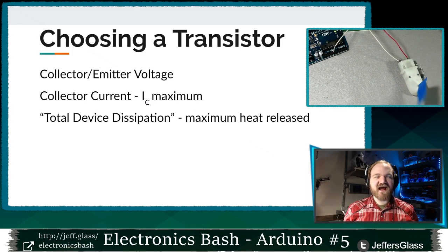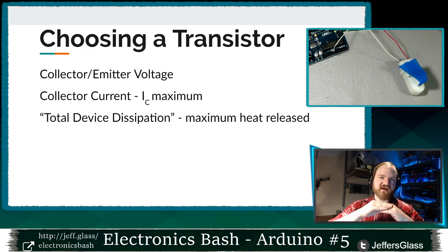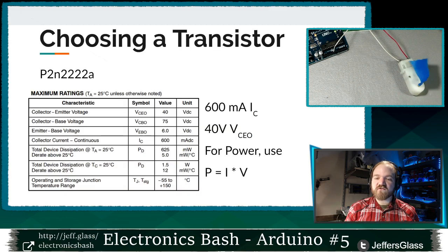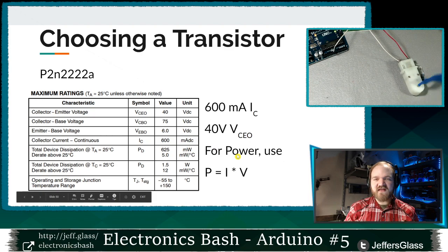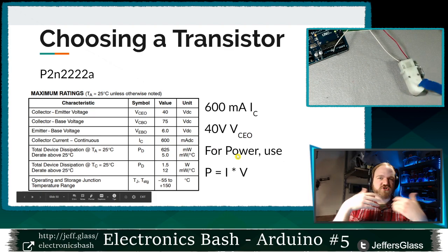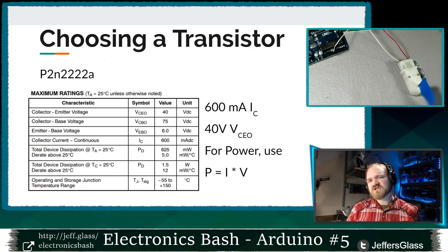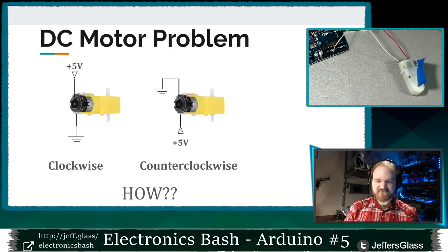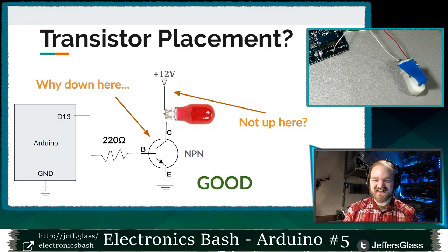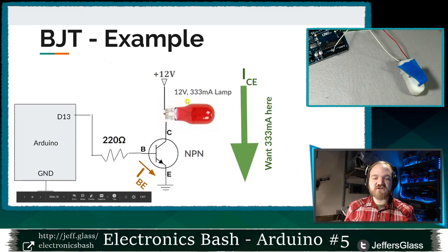what we're really interested in is how much heat this transistor itself is going to generate when it's in that current flowing state. The way we will figure that out is, you remember I said before that when the transistor closes that switch and turns all the way on, it has about a 0.2 to 0.3 volt drop across it. So let's go back to a circuit here. I didn't think to put a circuit diagram at this point in the slides. When this circuit is all the way on, I'm going to have about 0.2 to 0.3 volts across this transistor. I'm going to lose 0.2 to 0.3 volts in this transistor itself.